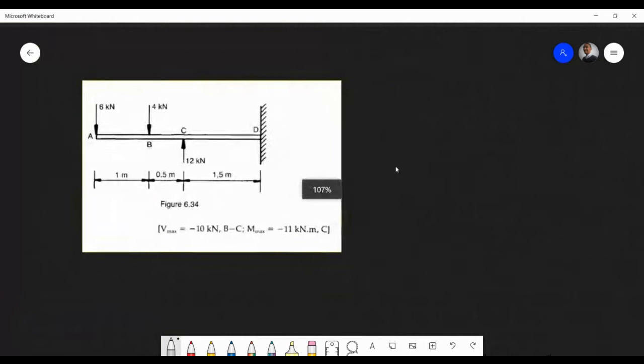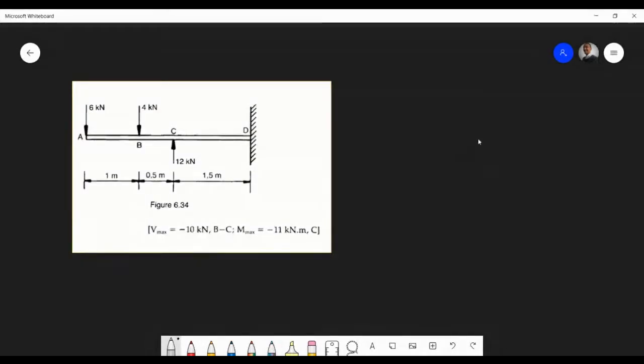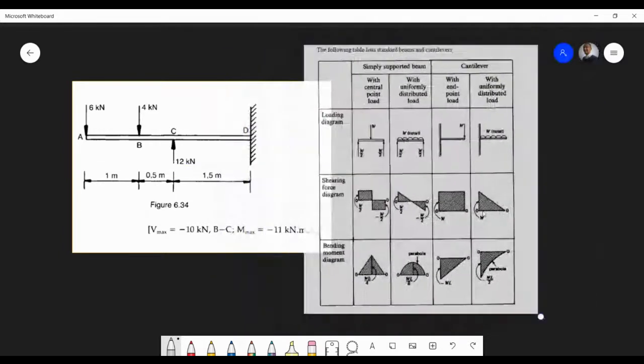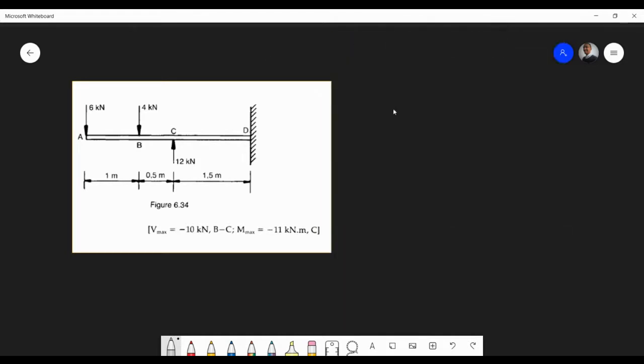Another thing you need to have in mind is that when sketching cantilevers, our bending moment diagrams look different, and they look like that. You've touched on these, and you'll be touching on these two now. Cantilever point loads will be fairly easy. It's exactly the same as the center point, and now we basically have these triangles. It's only when we have a UDL that we end up with these parabolic shapes. So that is clear to everyone. Make sure you show me those shapes correctly.